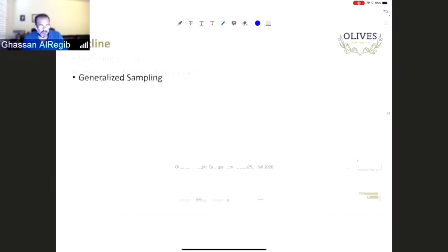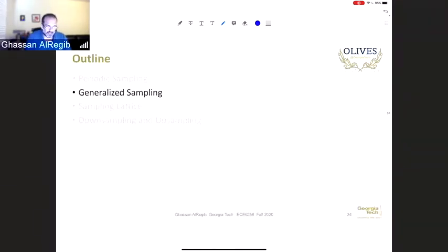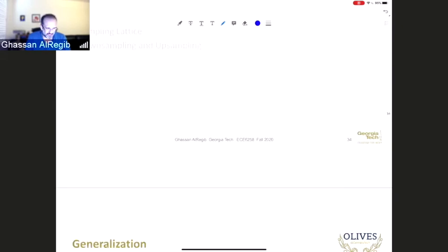Okay, so now what we'll move to next. Now we have the rectangular sampling. It's simple in the sense that it's a rectangular extension of the 1D case. So instead of capital T, we have capital X, capital Y. Everything else is the same in terms of conditions on the band-limited signal, as well as how we can reconstruct using the sinc functions.